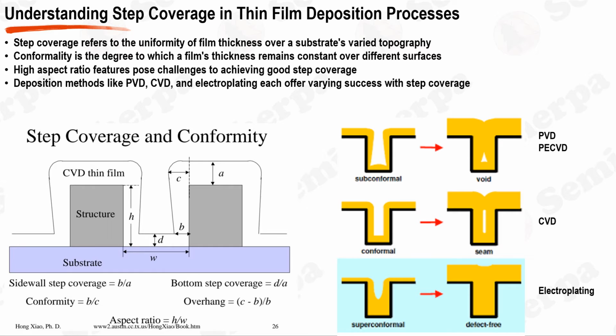In the realm of thin film deposition, step coverage is a critical metric to ensure the high performance of microelectronic devices. The concept pertains to the uniformity of film thickness across a substrate, even over intricate topographies such as steps, trenches, or holes. The degree of step coverage is often influenced by a complex interplay of physical properties, reaction rates, deposition temperature, and the concentration of reactants.